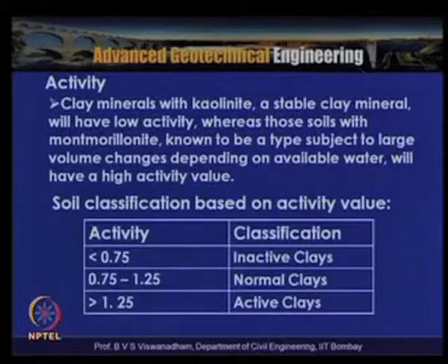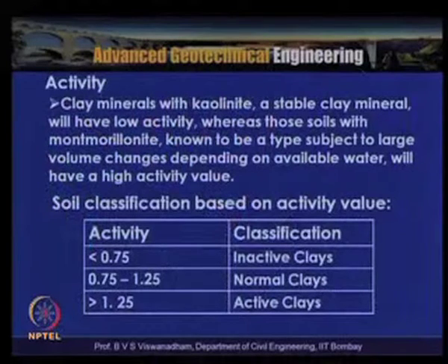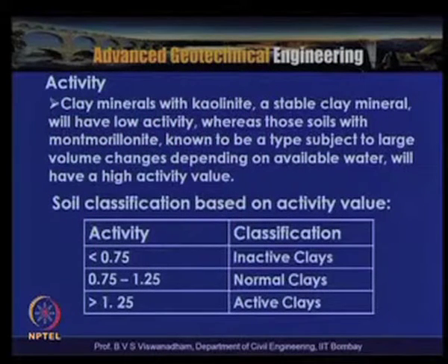When the activity value is less than 0.75, the soil is classified as inactive as far as expansiveness is concerned. 0.75 to 1.25, it is classified as normal clay, and greater than 1.25 is classified as active clays.